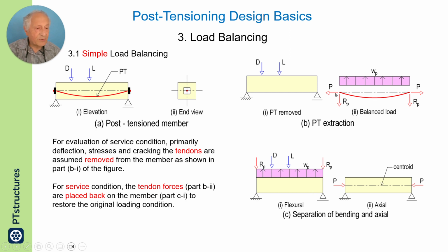And then you separate the axial force, here shown on the bottom right, and we argue that the axial force in simple load balancing results in uniform precompression, doesn't need any sophisticated calculation, and whatever we have on the left results in bending, as engineers knew it well and could handle it well, moments and shears and so on.